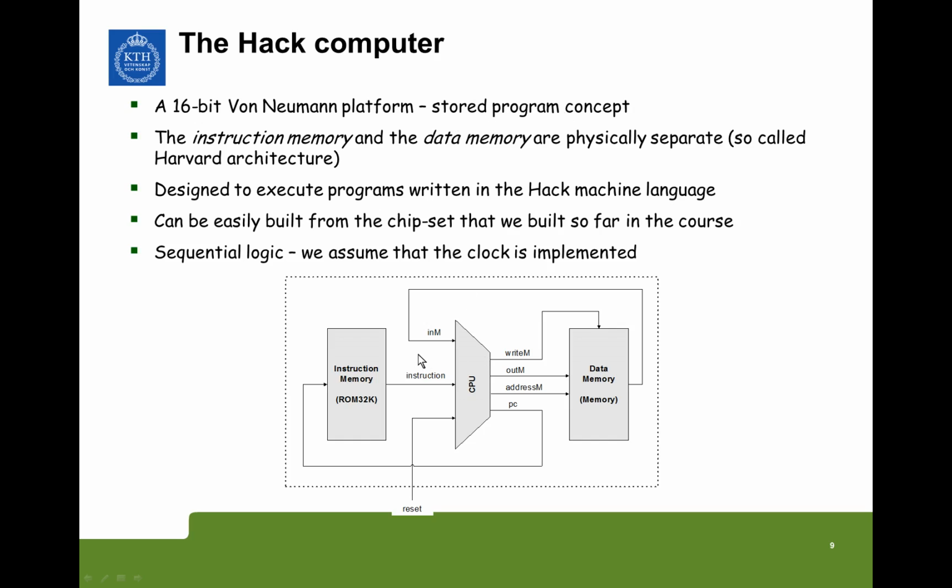Actually, the program will be stored in a separate instruction memory. So we will have instruction memory and data memory separated. It is actually the so-called Harvard architecture. We will design a computer that executes programs written in the Hack machine language.